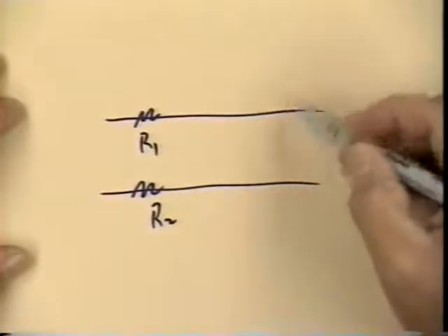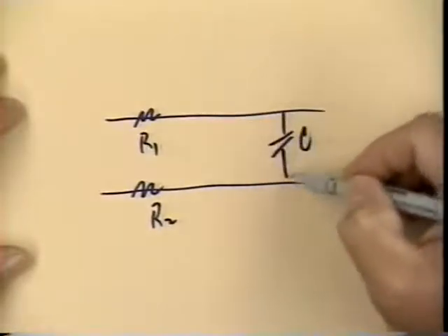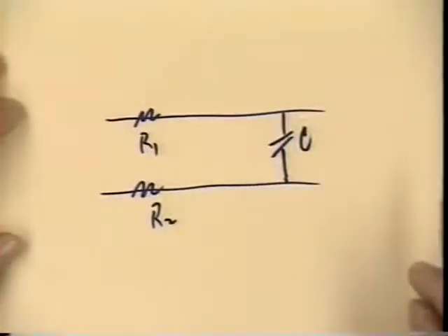Now, between the two conductors, there's one capacitance. We're assuming that either the wires are electrically short, or if they're electrically long, then this is the capacitance per unit length for a short section of wiring. So far we have two resistors, one for each wire, and a capacitance between them. That's the easy part. The hard part is the inductance. How do we think about that? Well, I think most people think about it incorrectly.